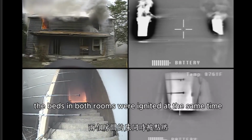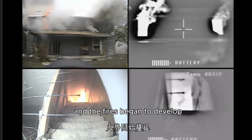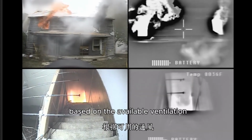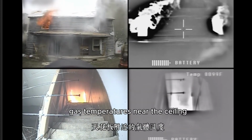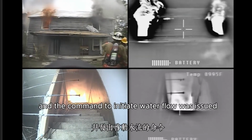The beds in both rooms were ignited at the same time and the fires began to develop. When both rooms had reached the fully developed fire stage, based on the available ventilation, gas temperatures near the ceiling were in excess of 1,000 degrees Fahrenheit, and the command to initiate water flow was issued.